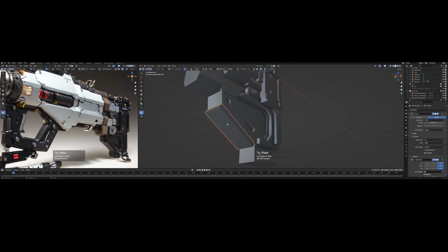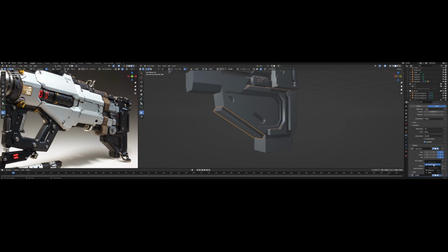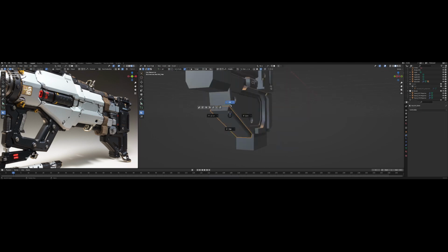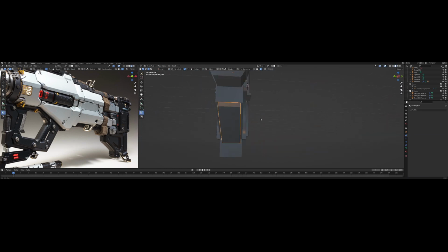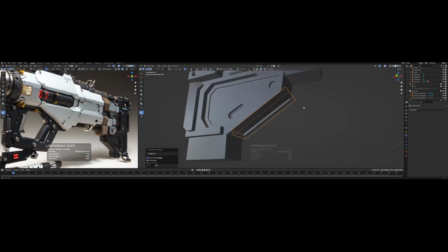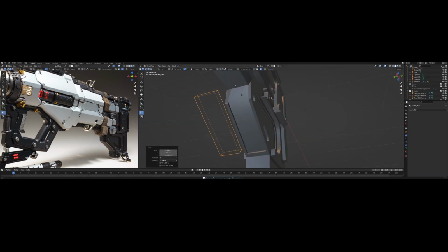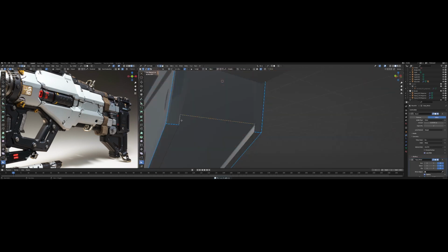To make those steps, I think it will also be pretty easy. With Hard Ops, you just select a single face and go to curve extract, and holding Shift, you press that area, and a solidified mesh will be created automatically.